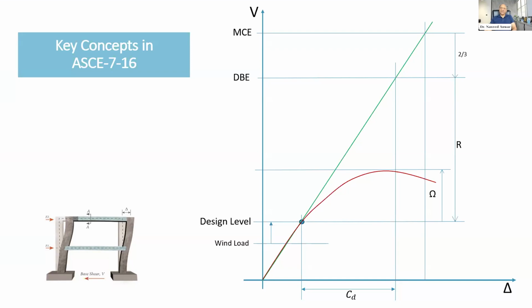The second one being that the actual material strengths are typically larger than we specify for steel strength and concrete strength. They age also, and they get better over time. But more importantly, because of the grouping of structural members, not every member is designed at the capacity. We group them, so many beams and many columns will be above that, because we can't keep changing reinforcement for every member. So we take the critical one and we apply it in many groups. So the overall capacity of the structure will be much greater than the visual capacity of the members. So that's why this overstrength factor is added.